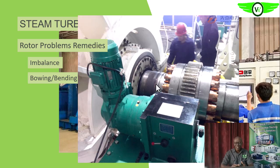Are we getting it? Then during startup too, as you are administering steam, especially on those bigger steam turbines, you have to keep turning the shaft so that it will be heated evenly round the rotor. So to help us achieve this, we have the turning gear.